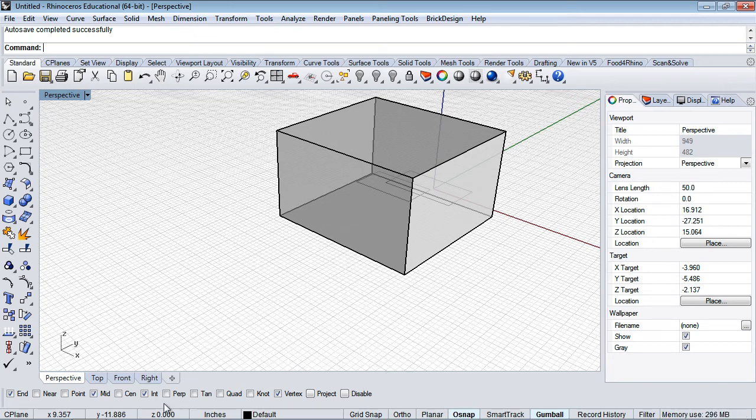All right, so here is that piece, and then what we can do is, let's say we want to create a line. Now we can snap to this geometry. So now it's telling us we're at an intersection between lines, and it's also the endpoint of the line. If I come over here, it's snapping to the midpoint of the line. Okay, so those are all wonderful things.